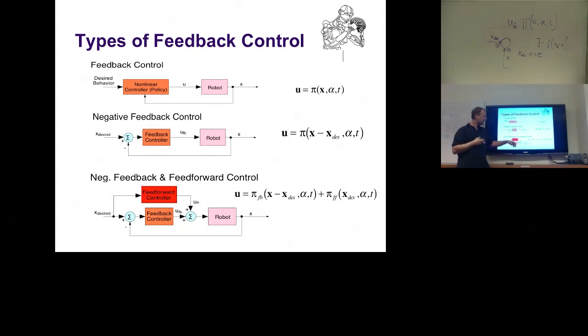The feedback controller is the error correcting controller. Remember, the feed-forward controller has no feedback. Here, the signal is directly coming from the desired state, going up here to the feed-forward controller, and then to the robot. It does not get feedback from the environment. So in this way, the feed-forward can only give you the right amount of pushing forward. The feedback controller does the error correction, which is really important. Without error correction, you cannot be stable. Without someone telling you how much you're off from your target, you will not find home at some point. So if you close your eyes, you will just deviate more and more and more, and instead of going to downtown, you will end up at the coast.